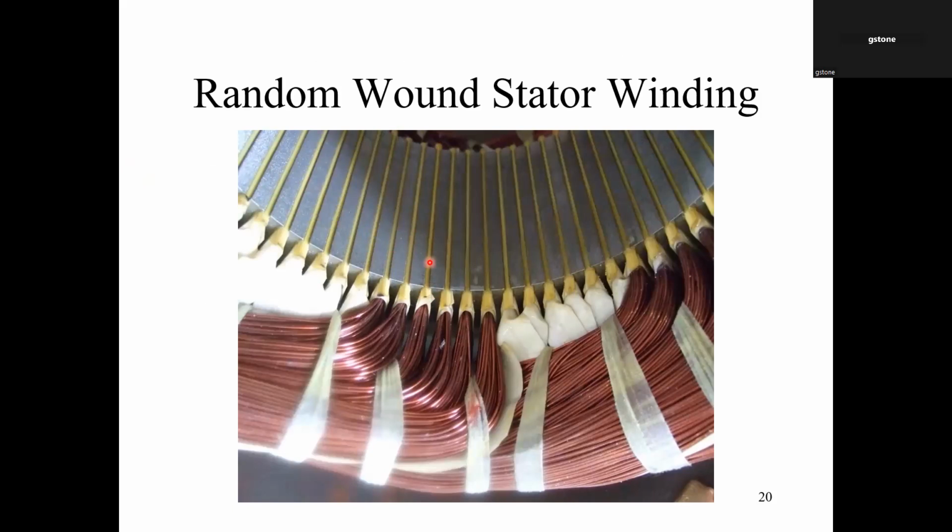But it's insulated copper, and where the insulation is a polymer film, one of the common ones being polyamide-imide. Okay, and that's that brownish purplish material you see on motor windings. And the big issue here is why we call it random wound: that conductor from one turn in that coil can be adjacent to any other possible turn in that coil. There's kind of a random placement there. And this is what can sometimes cause us some problems.